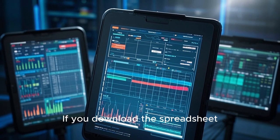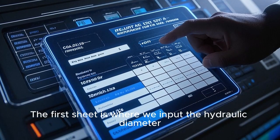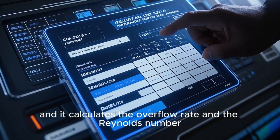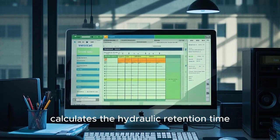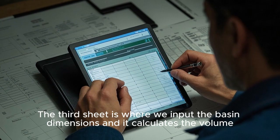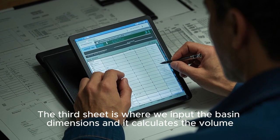If you download the spreadsheet, you'll notice that there are 3 sheets. The first sheet is where we input the hydraulic diameter, and it calculates the overflow rate and the Reynolds number. The second sheet is where we input the overflow rate and the surface area of the basin, and it calculates the hydraulic retention time. The third sheet is where we input the basin dimensions, and it calculates the volume.